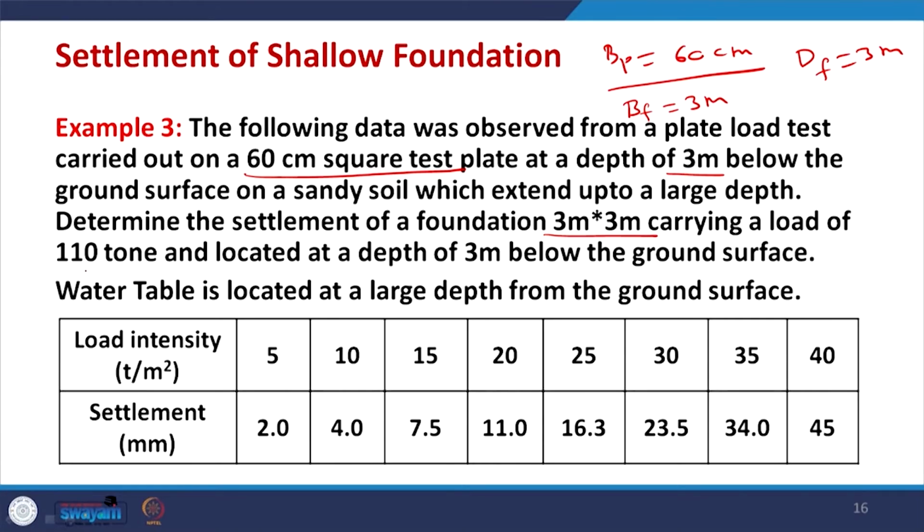It carries a load of 110 ton and is located at a depth of 3 meter below the ground surface. So the depth is common. In the plate load test, the plate is kept at the same depth as the footing, Df. Now, using this data, first we prepare a load settlement curve, which is shown in the slide.